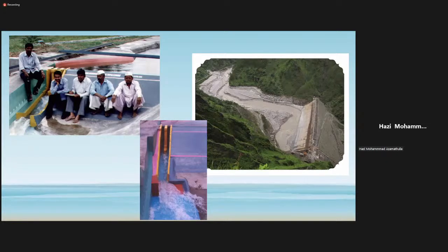So here also, due to high velocity jets, the right bank is having so much problem. So you can see downstream we have provided one deflector, and also curtailment of the flow: a right hand side deflector and some left hand side curtailment. So the flow can easily spread like a spray. Okay, so this is the problem here. Okay, next slide please.